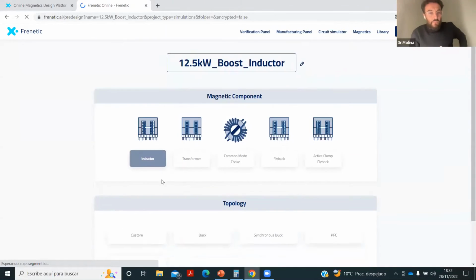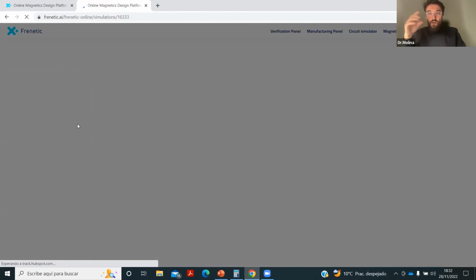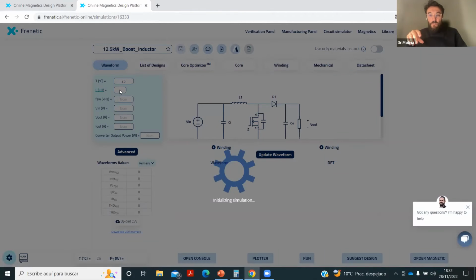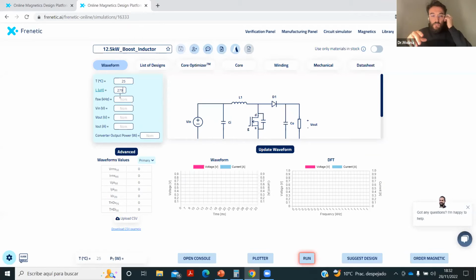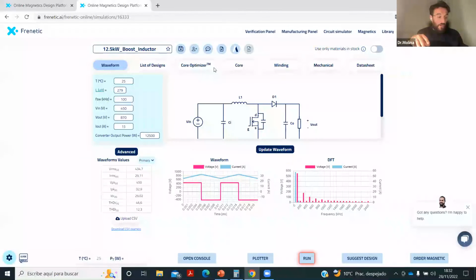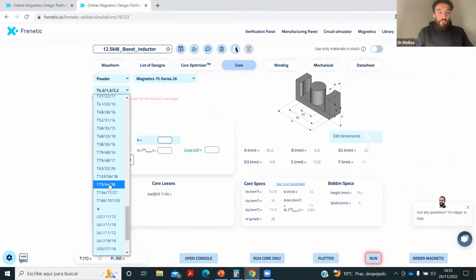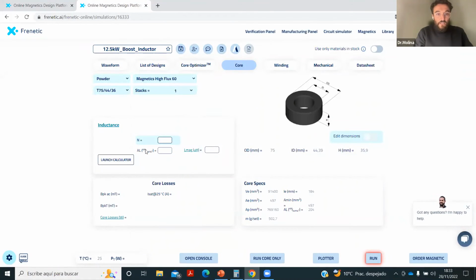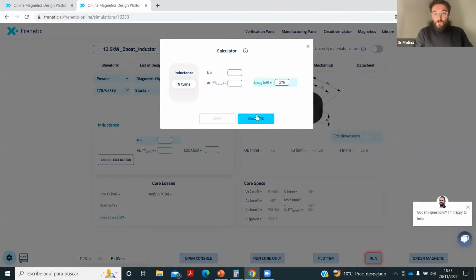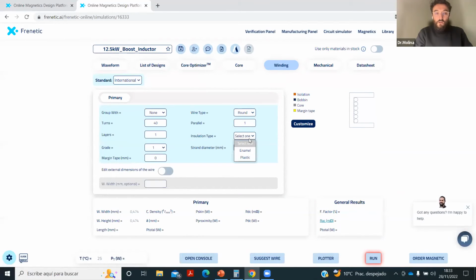In any case, something interesting is that for the smaller inductors, you can analyze a lot of options, and at the end the main limitation is the height or the dimensions, and then you just need to filter. If you have a great database of components, you can have a lot of options. This is good, especially nowadays that we are out of stock in a lot of cases. And for the high current inductor, it's very similar at the end. You just need to ensure that what you are looking for is also in stock. I think this is quite important for doing the calculations very fast and ensuring that you are not losing your time.